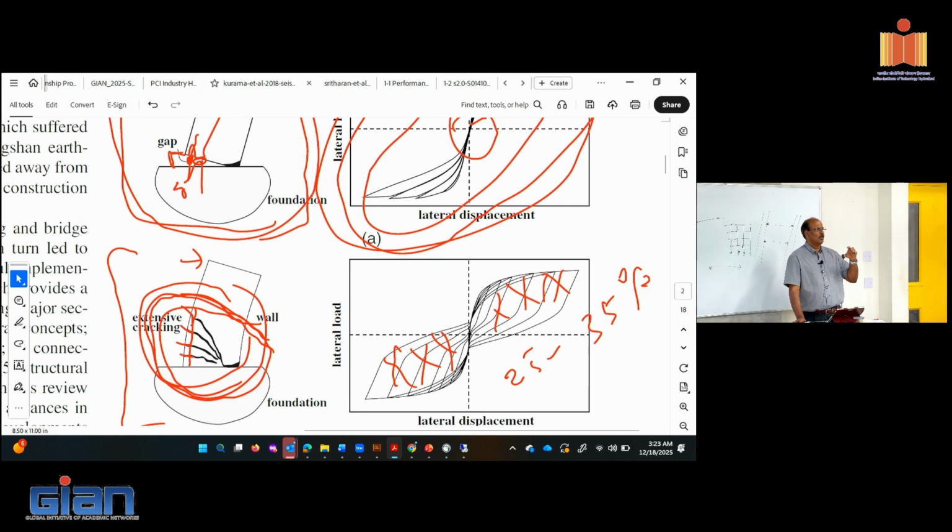So you also calculate how much distribution you're going to have. So you can control how much debonding you want to do, and therefore how much energy dissipation you will get out of it. All of that you can control. You can also decide between post-tensioning and the rebar, because both provide moment resistance, how much should be resisted by post-tensioning and how much should be resisted by rebar. You can mix and match to establish your desired system.